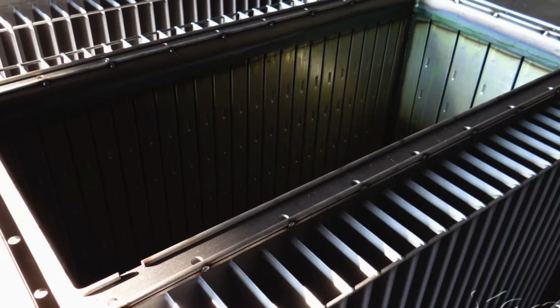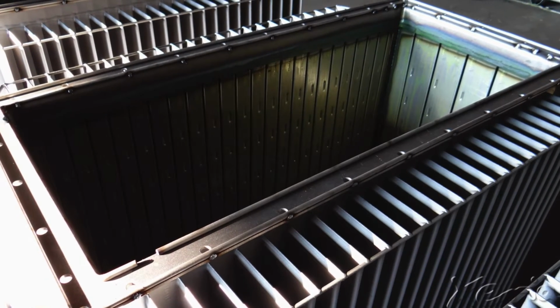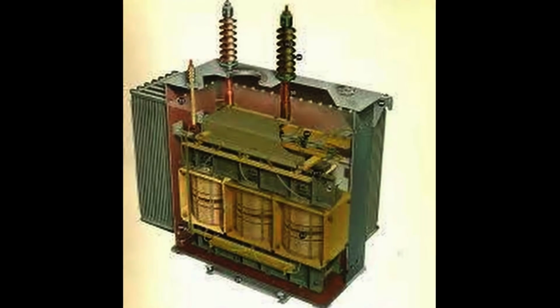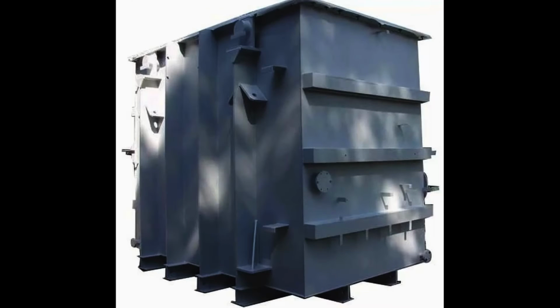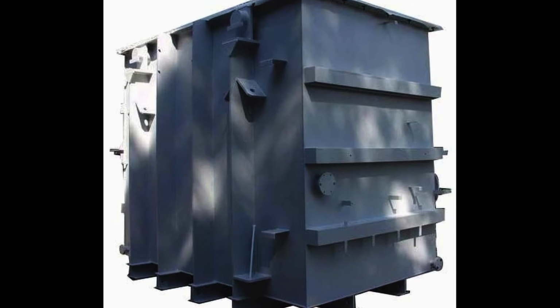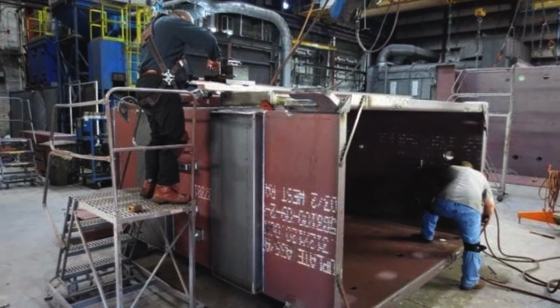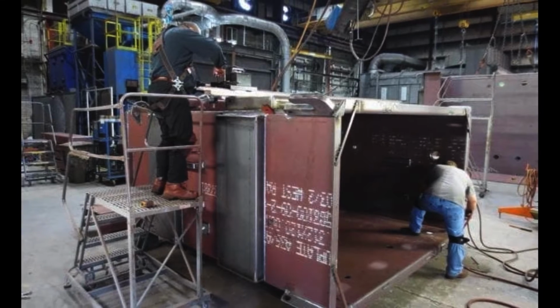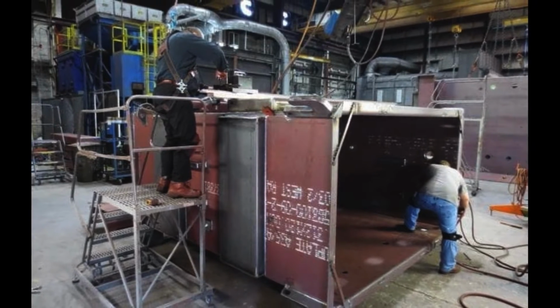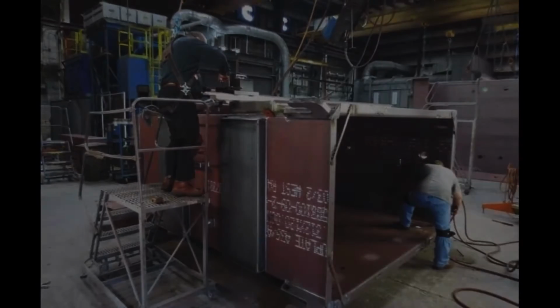The steel tank of the transformer holds all of the cooling fluid and is pressurized. It holds all the active parts of the transformer. It is usually bolted to the pad with concrete anchors. There are stiffeners along the walls of the tank that strengthen the tank against the pressure, vacuum, and other forces it is subjected to. The stiffeners allow thinner steel to be used in constructing the tank walls, which reduces the unit's weight while maintaining the same structural integrity as thicker steel.